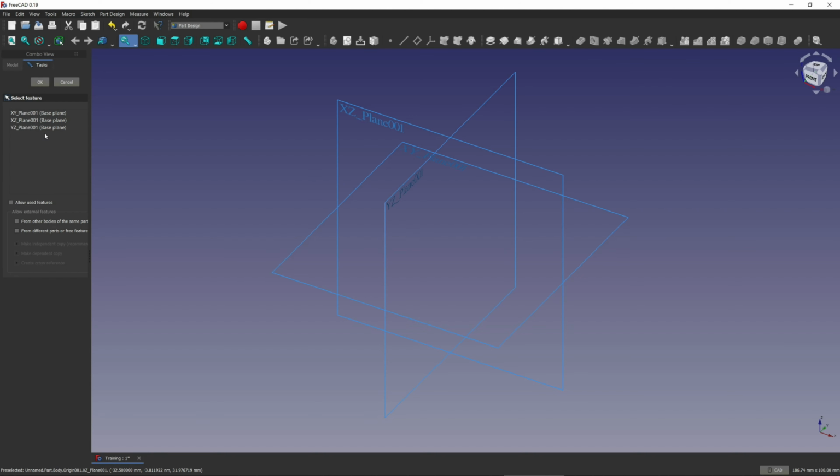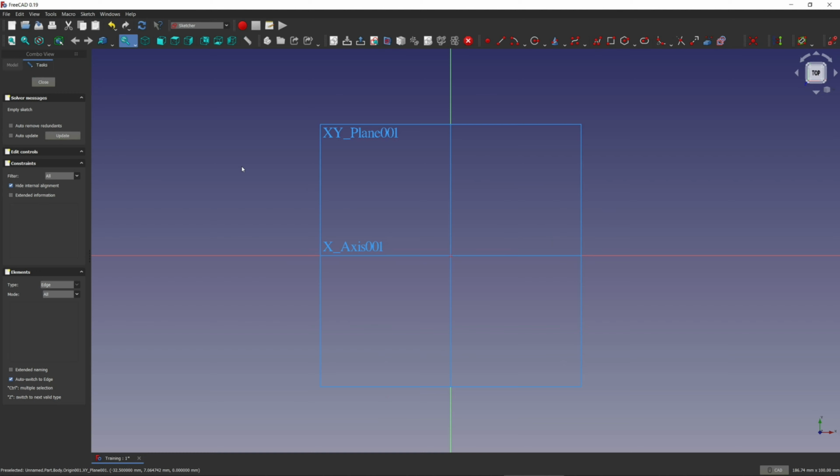When you create a sketch by clicking that button at the top, you then have to choose a plane. You have 3 options: your XY plane, your XZ plane, and your YZ plane. For the purposes of 3D printing, which is what I'm learning this for, we're always going to use the XY plane, because that is effectively your print bed when it comes to exporting this model as an STL and then importing it into a slicer. So you select your sketch, you select the XY plane, and then it will take you to this screen.